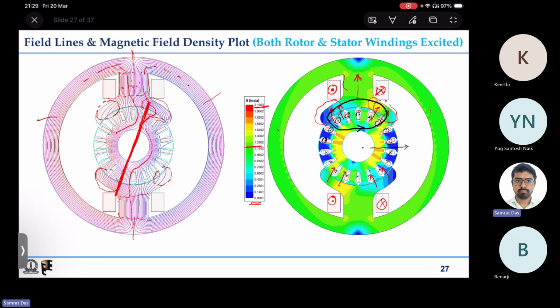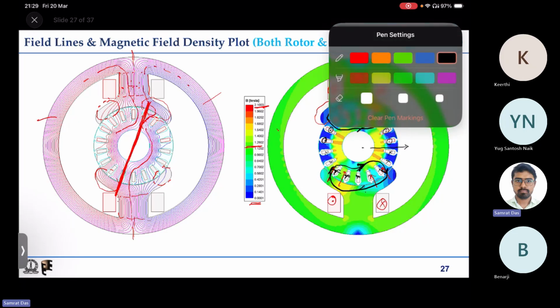That is the path taken by the armature flux, right? So here you have all the cross conductors. Because it's cross conductors, it will be right hand side here, so it will be clockwise. So you have arrowhead direction like this and arrowhead direction like this, whereas on this side it is radially outward, it is radially inward here.